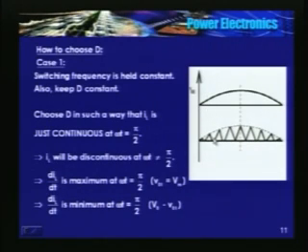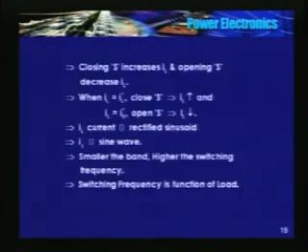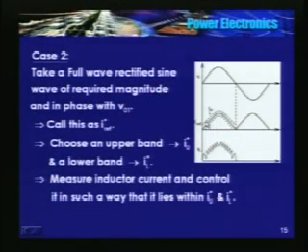The power factor is 1, so the entire unit looks as if the source is feeding a resistive load. Now if you see in the circuit, the smaller the band, the better the source current waveform. Smaller the band, it looks as if the current is a sinusoid itself.